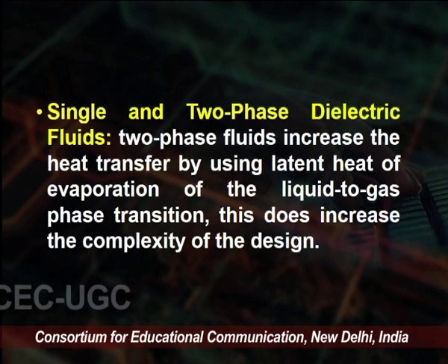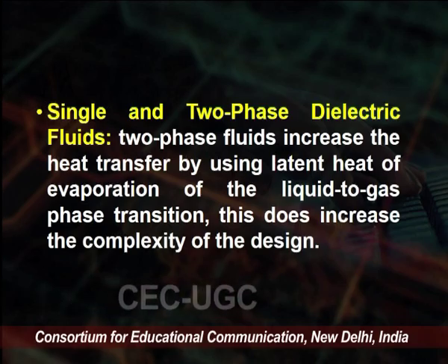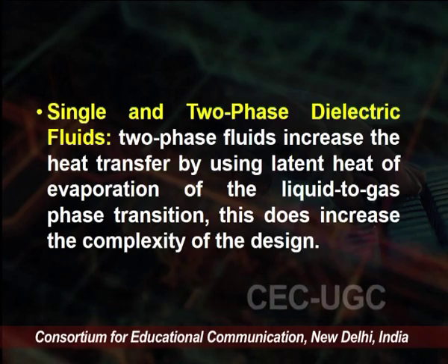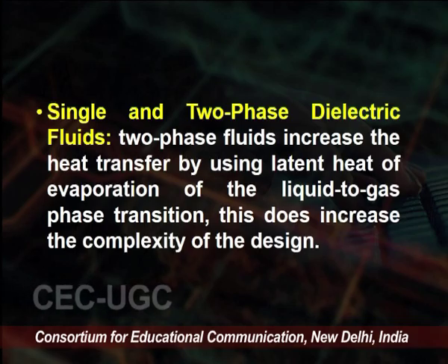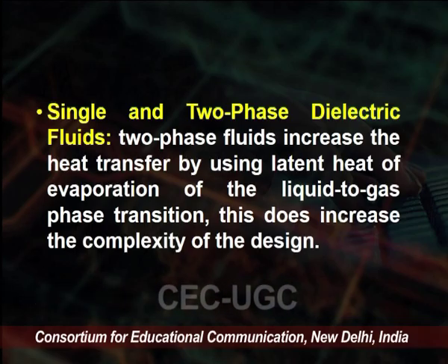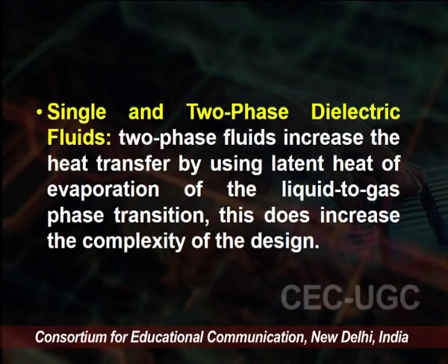Here the dielectric fluids are divided into two parts. First is single phase, second is two-phase dielectric fluids. Two-phase fluid increases the heat transfer by using the latent heat of evaporation of the liquid to gas phase transition, and this does increase the complexity of the design. So it works with single as well as two-phase dielectrics.